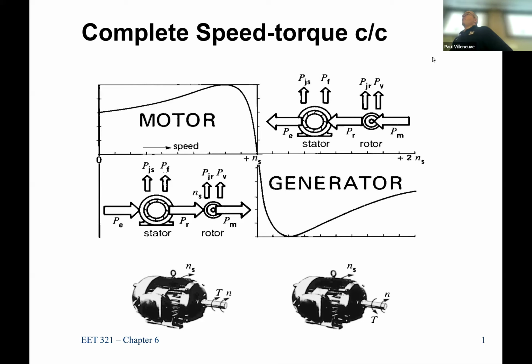So if you look at more of the wind turbine facilities now, they have to have the capability of providing voltage. It's called low voltage ride through. They have to provide voltage support for, I can't remember if it's 1 second or 10 seconds, but it's a fairly long period of time. And there's two ways to do that. The first way is they call dynamic var compensation.